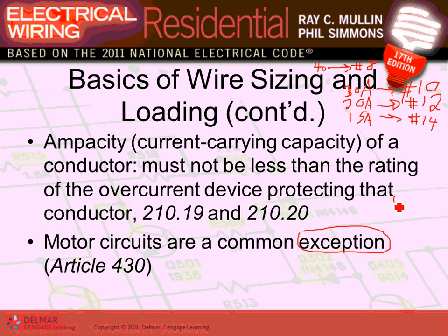Still red. Between these 2 guys together, you got yourself 80% of your loads. 80% of your dwelling loads, circuits, are 20 and 15 amp circuits. The 30 amp, your 30 amp here, we have an AC, and the 40 amp is for what? Range. Done. You have just circuited the whole house.